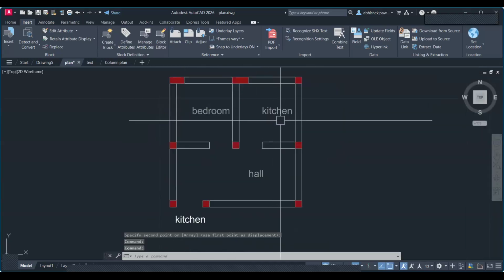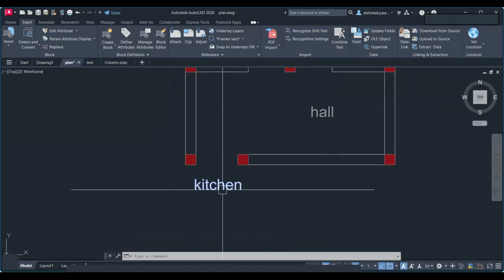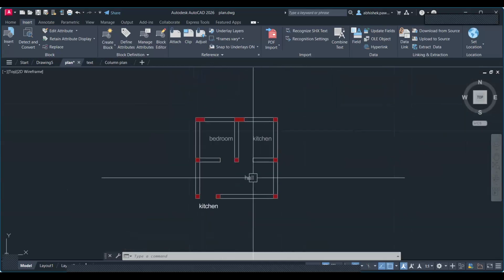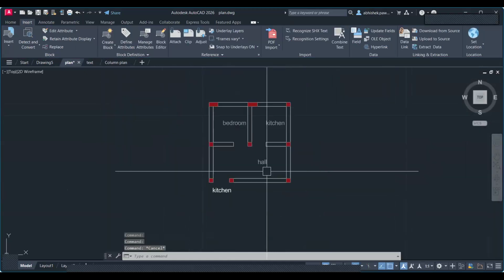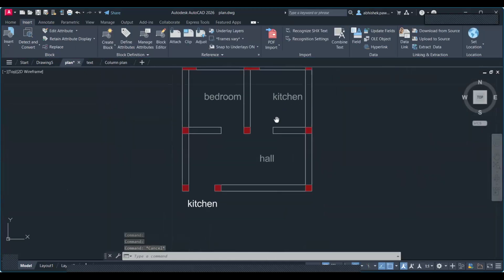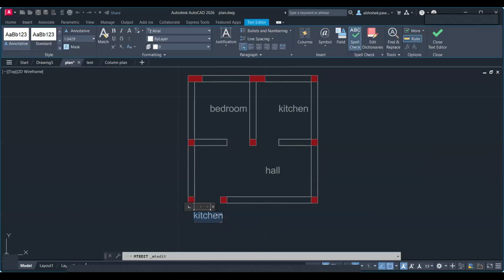See, the things got detached from this xref and are live in my AutoCAD. Right now it is not live, it is an xref, but after using the NC command, we can use this as an AutoCAD entity in my current drawing. Now I need to change it. Control A, tell it main gate.